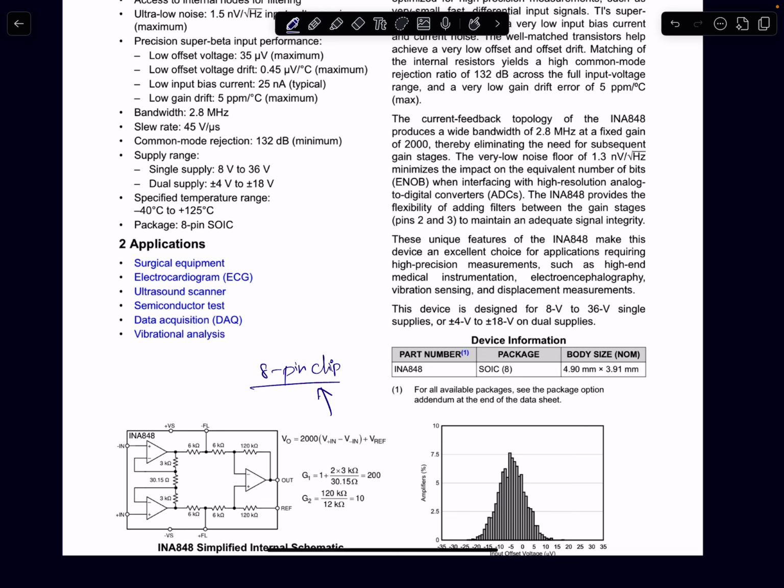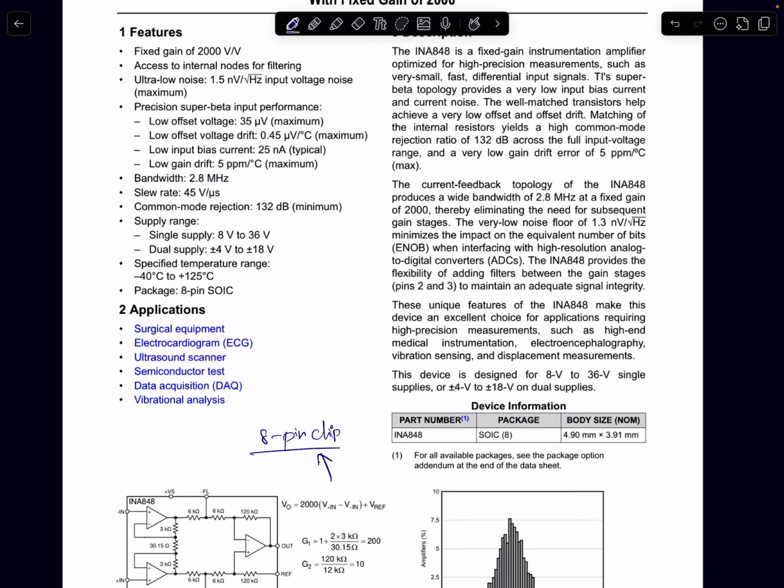They are manufactured within a single chip, and they are well designed for accuracy. They are all very well designed. They are well matched on the chip itself. So their CMRR by default will be very, very good. And you can see here, the minimum CMRR is 132 decibels, which is higher than what we saw in the previous example. Okay, so this is a very high CMRR. And therefore this chip is naturally priced higher. It's priced, I think, 2-3 times higher than the price of the previous chip.